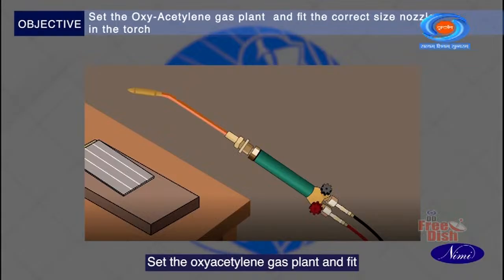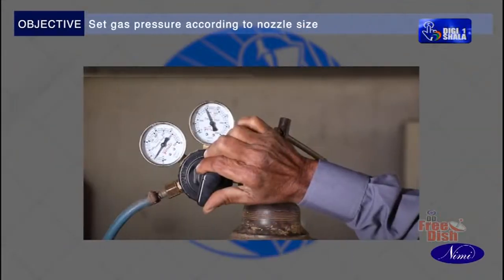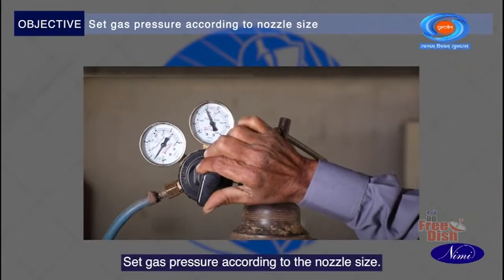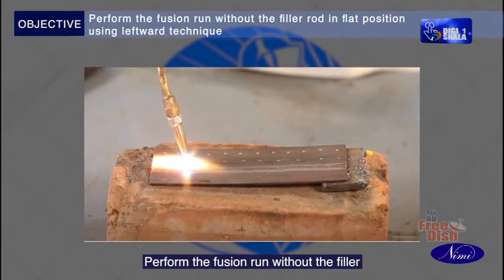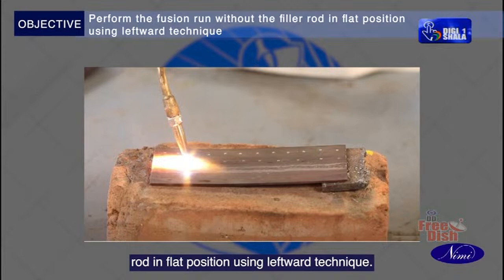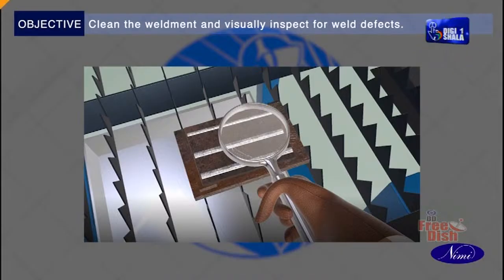Set the oxyacetylene gas plant and fit the correct size nozzle in the torch. Set gas pressure according to the nozzle size. Perform the fusion run without the filler rod in flat position using leftward technique. Clean the weldment and visually inspect for weld defects.